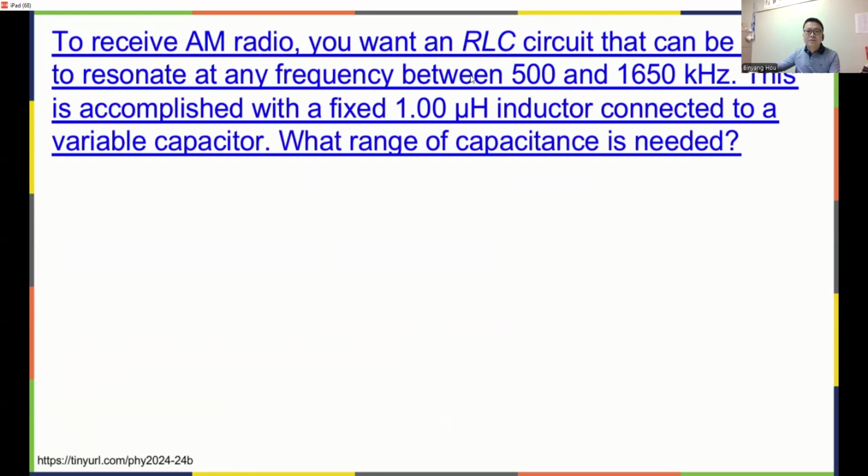If your frequency matches up with the radio signal, then you get resonance of the signal in the circuit. The signal will be enhanced, and other frequencies will be suppressed. That's how the radio works.